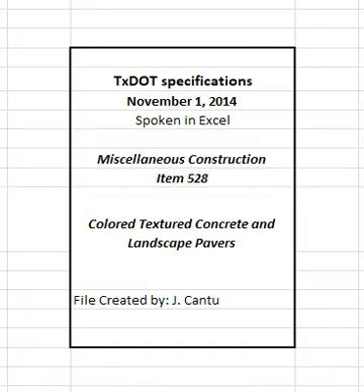When approved, use fibers listed on the department's MPL or fibers meeting the requirements of DMS 4550, fibers for concrete, to replace reinforcing steel in Class A concrete. Use approved dry shake color hardener or integral concrete colorant shown on the plans. Provide colored wax as a curing membrane meeting the requirements of ASTM C309 or as shown on the plans.